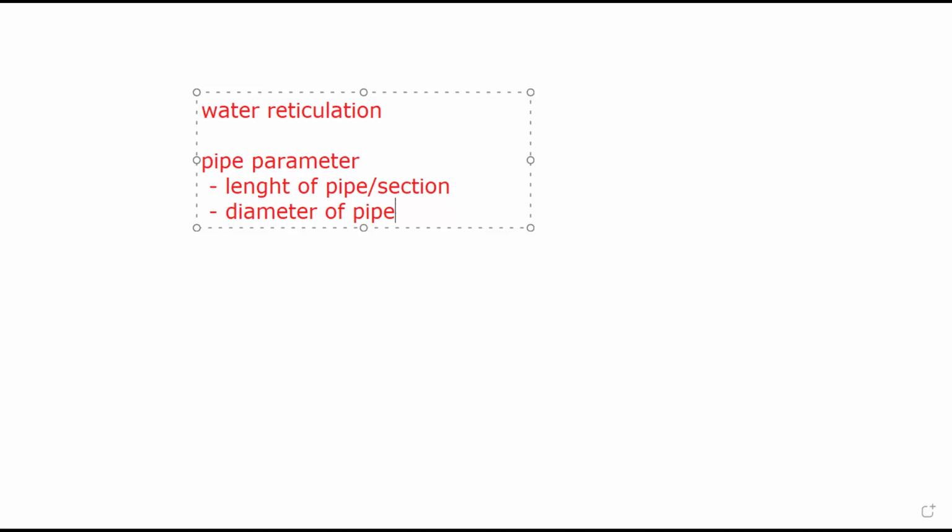The minimum should be at the tail end. At the upstream, you can have as high as 6 inches, 150 mm. Then as it's going down, it's reducing. Can reduce to 4, can reduce to 3. But I can tell you, the one that gets into the houses or anywhere, field, market, shopping or whatever, should be at least 2 inches pipe.